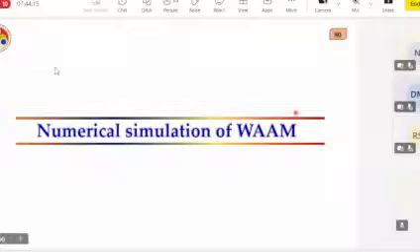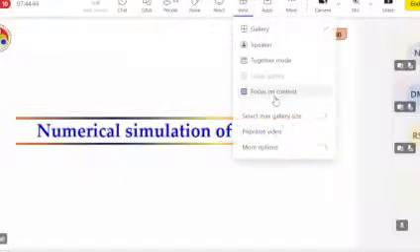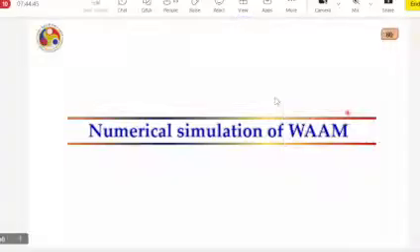For writing the user subroutine, you have to go to load, and if you go to edit load, there you can select the distribution as user defined, and there you can select this particular Fortran code, basically a subroutine written in the Fortran language. You can define all the parameters, then define the double ellipsoid model, and then directly load it over here, and then it is called by the program during each simulation.